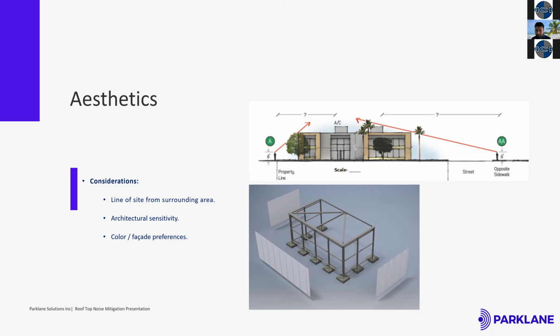If it is a bigger duct, then even though there's a lot of surface, there's not a lot of absorption through it, whereas the smaller duct... it's really the property of the duct. It doesn't have anything to do with the NC rating.